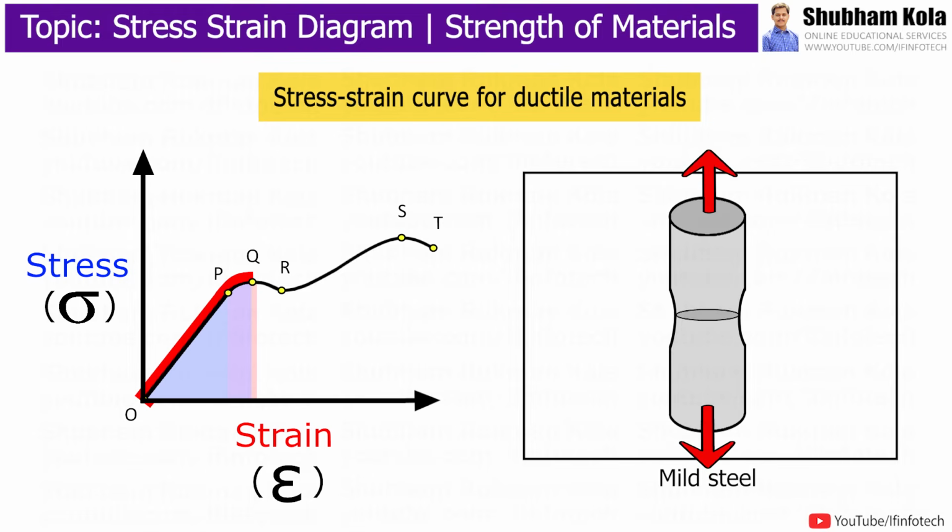Beyond elastic limit, the material enters into plastic zone, and removal of load does not return the mild steel bar to its original dimensions, thus subjecting mild steel bar to permanent deformation. On further loading, the curve reaches point R, called upper yield point, at which sudden extension takes place, which is known as ductile extension, where strain increases at constant stress, shown by horizontal portion of diagram.